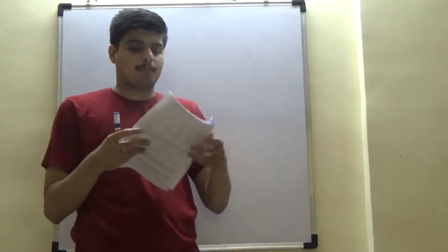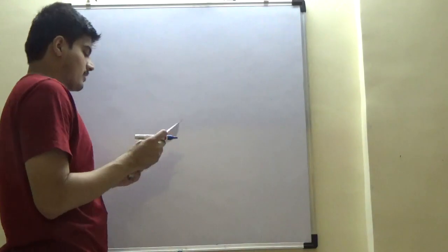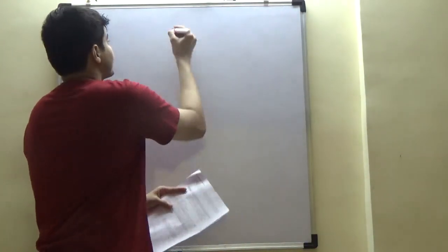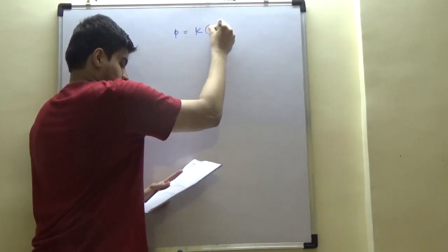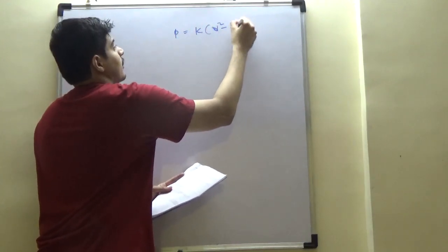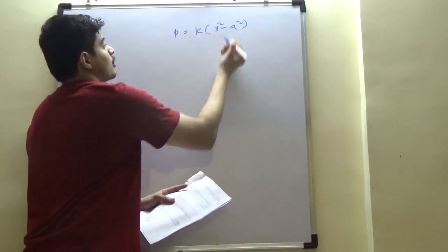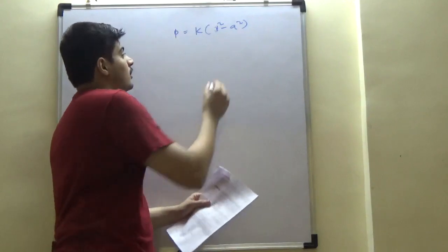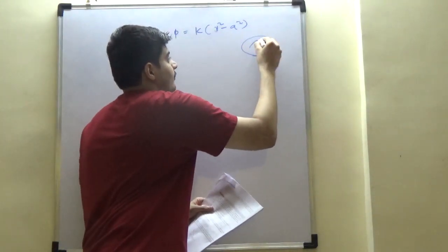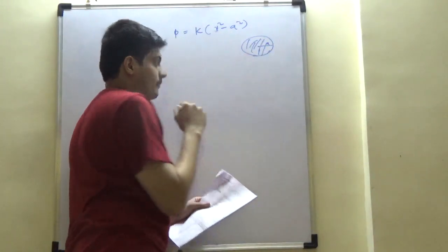The second practical problem which we will look at is, we have already seen this, but we have to find out now. For a circular cross section, K(r² − a²) is a valid Prandtl's function. This stress function can be applied to a solid cross section which is circular in nature, of radius a.